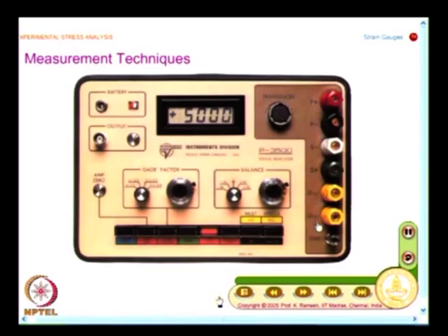See, in one of the earlier classes we have looked at, when you are using a Wheatstone bridge, if I have to maximize the signal from the Wheatstone bridge, I should use R1, R2, R3, R4 having the same values, and we have seen strain gauges are available at 120 ohms and 350 ohms very commonly, and you can use 120 or 350 for various applications, and depending on the strain gauge that you select, you must also have the other resistors selected in the Wheatstone bridge.